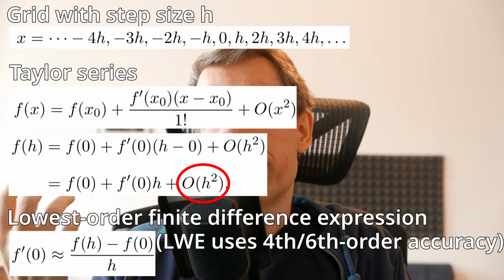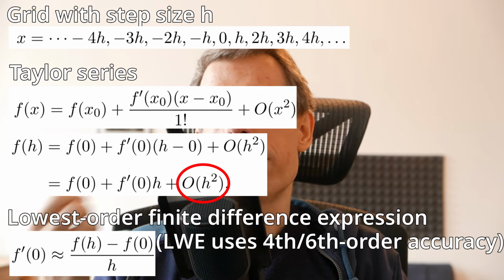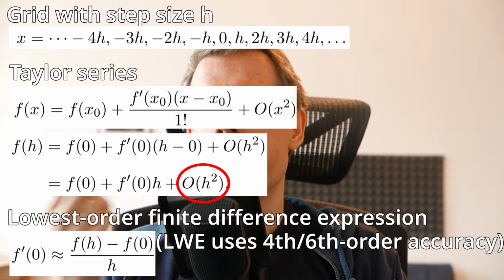So we can find out, well, are these errors dominating the answer that I'm getting to whatever question I'm asking the numerical simulation. So really in the end, what we need to do is we need to look at some observable quantities about the simulation and make sure that they're not changing as we change properties of how we set up our numerical grid, as long as the properties of the numerical grid shouldn't affect the result.